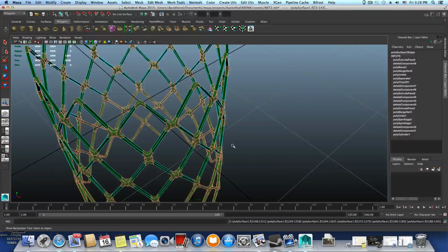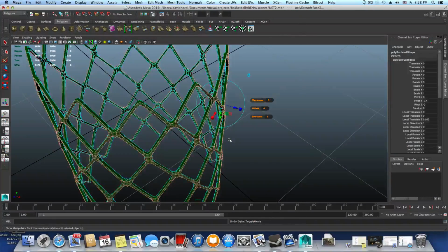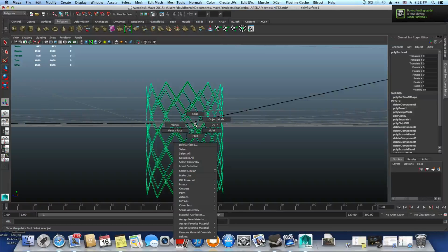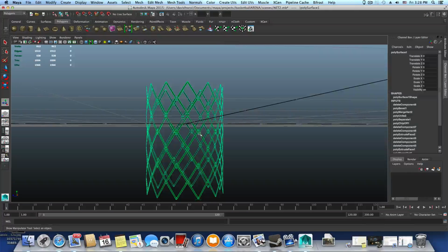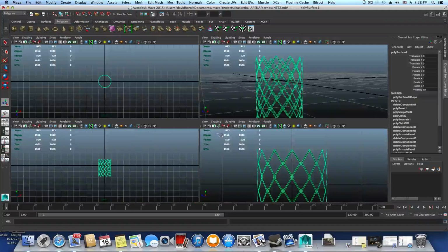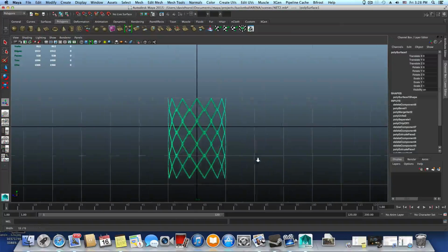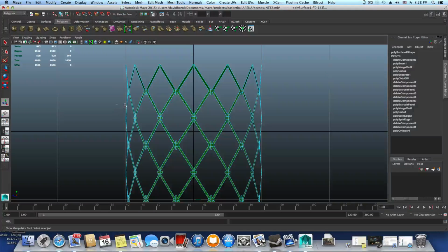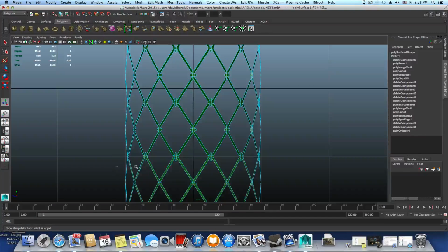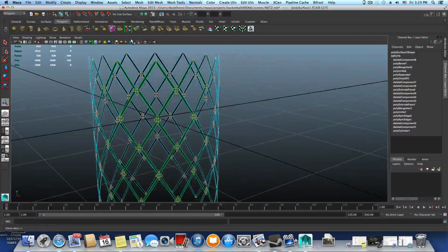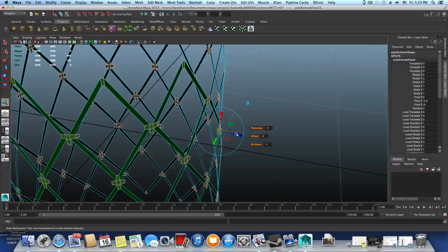And in order to avoid this, basically, I should stop exactly where I started. So I don't want to extrude that in the first place like I did. So what I will do this time is start off by extruding only the connection points, while it's still flat and has no thickness. I'm going to go over to side view and select them again. Right click, face, let's grab all the faces, control, area, and so on. Okay, go over to perspective view, extrude this, and now you will see what happens when I'm extruding faces that way.